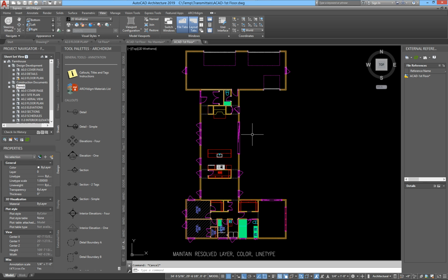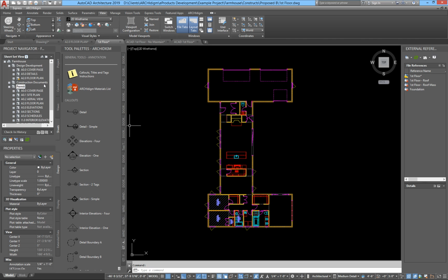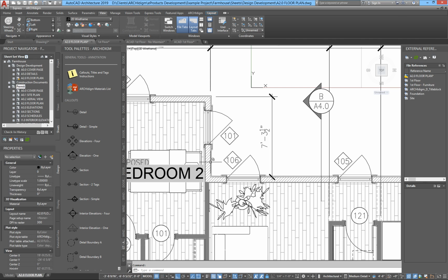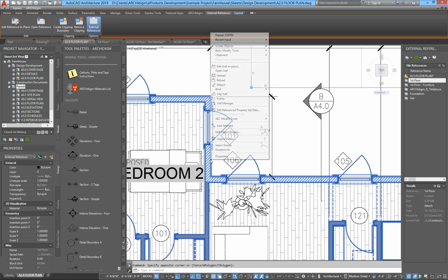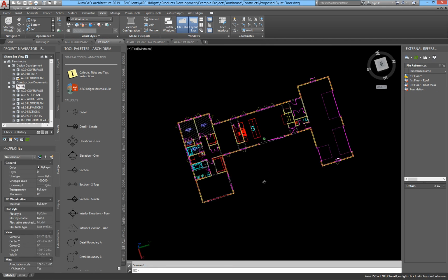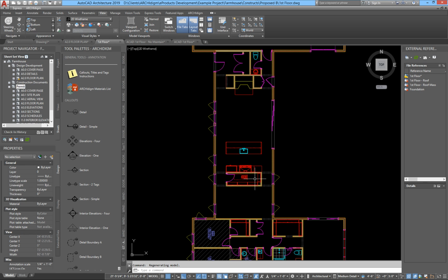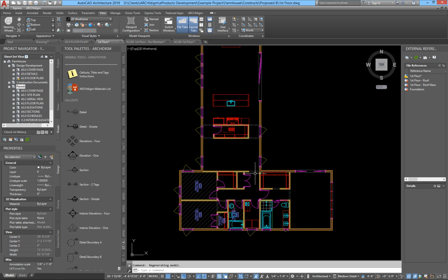Okay, now those masks. If I go to the original file, let's see, do I have it here? Let's go back. Okay, so I'll get my original file. So this is the real deal. This is the BIM, and I don't want to screw up my BIM, so I never save when I do this kind of work. I'll just configure it and do the conversion and then not save.